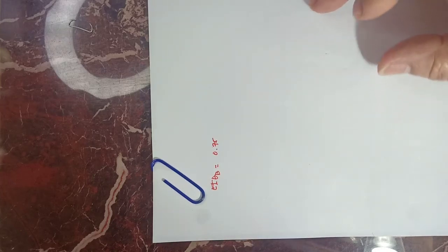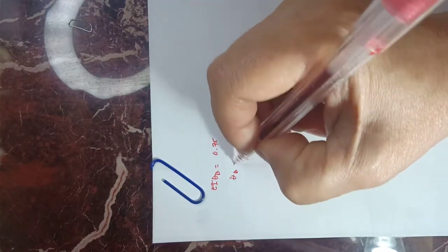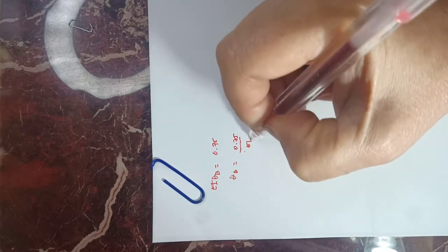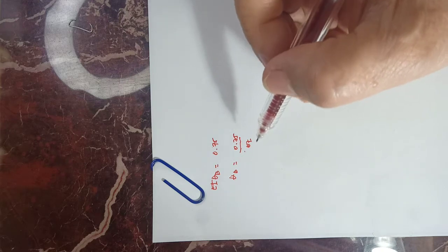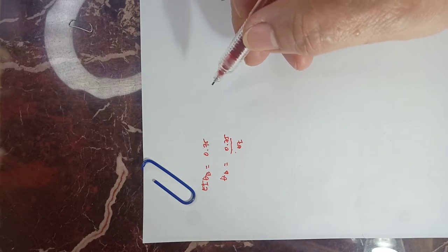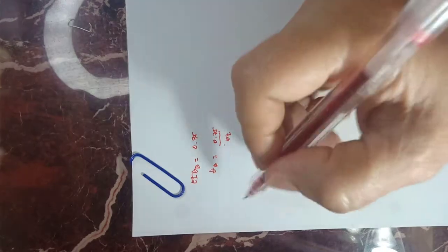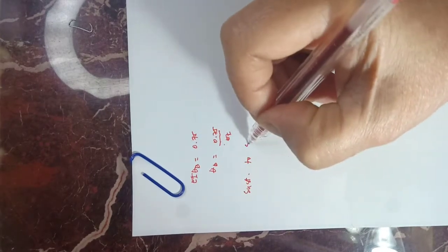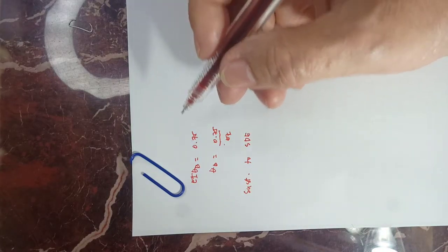Okay, so we have now EI theta B equal to 0.75, and solving for theta B, that would be equal to 0.75 over EI. So actually, this is the slope at B. If E and I are given, we can determine the slope at B in radians. Okay, so we substitute it back to the slope deflection equation, so that we can now determine the end moments.